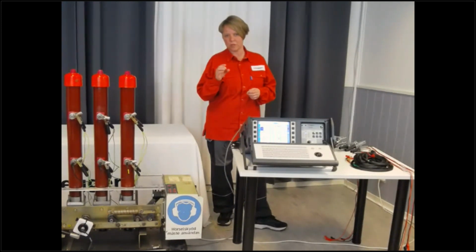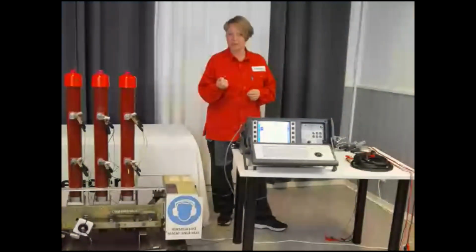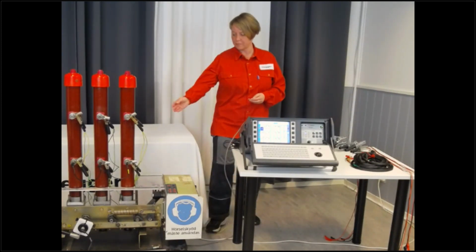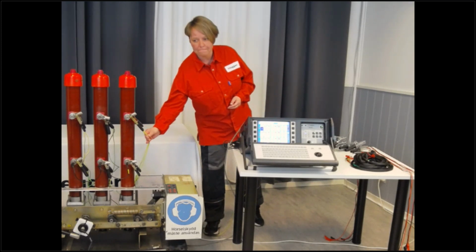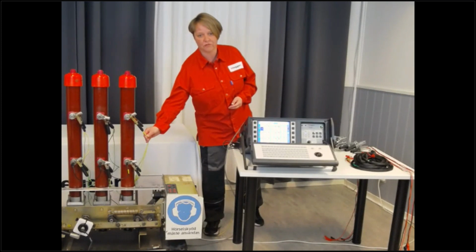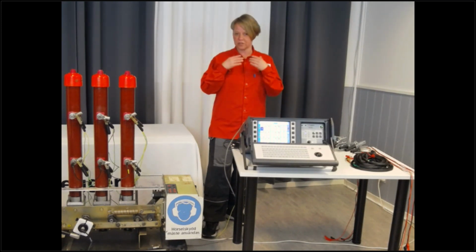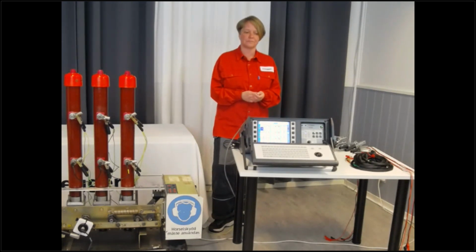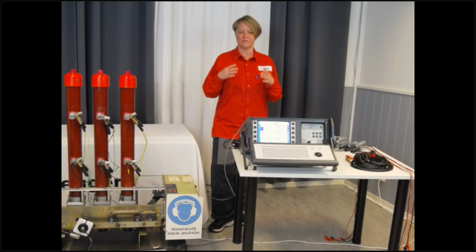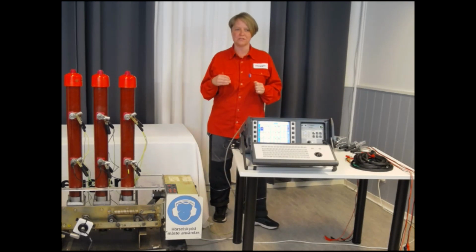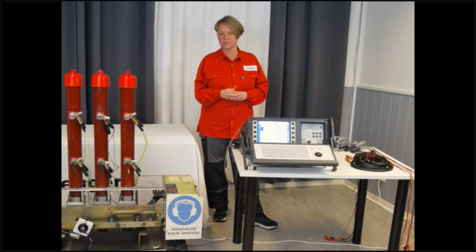units which have a very high inductive material, which influences the resistance. It's not the resistance, it influences the whole inductance of the circuit through ground. So we put them over the ground to change, not the resistance actually, but the circuit to ground. You could also use a longer grounding, but in a GIS, the reason why the ground resistance is not enough is that the whole pipe is grounded. So the pipe is working as part of the ground. The resistance in the pipe can be lower than what you're trying to measure inside. So when you do a resistance measurement, that also influences if you try to do a timing result.